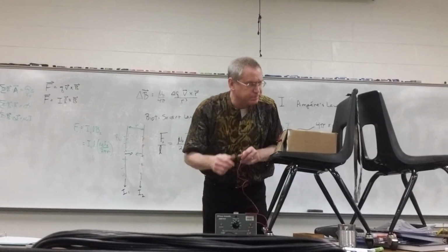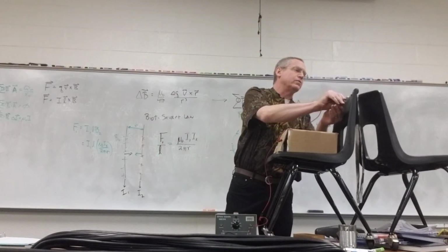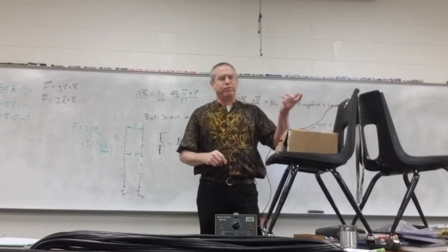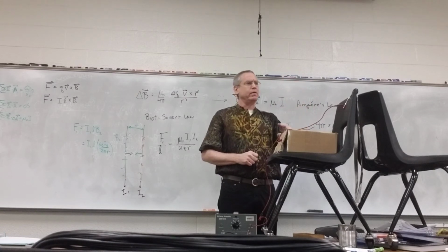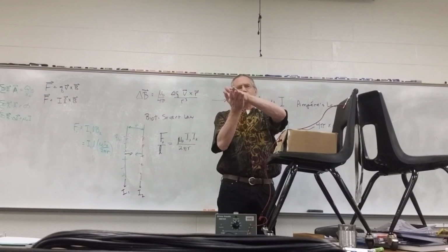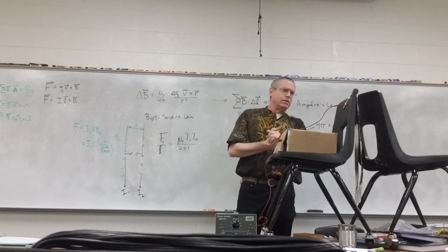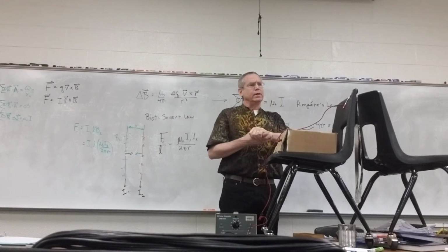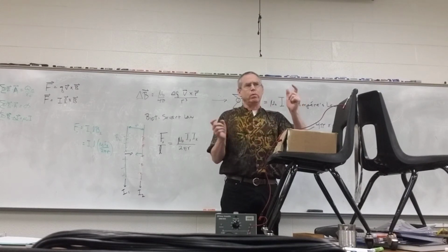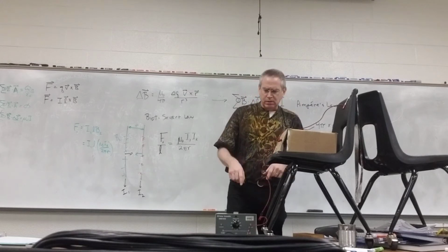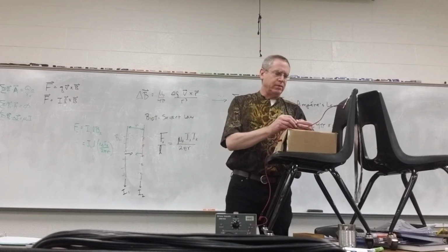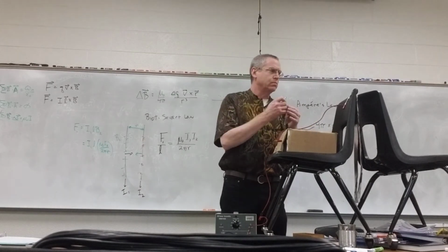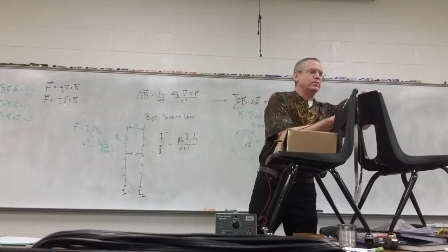This is turned off, right? Yeah. Now, one thing about this is because this is just an aluminum strip of particular length, remember that resistance depends upon resistivity times the length divided by the area. There's not a lot of area there, it's a flat piece of aluminum foil, and the distance isn't very long. And so, primarily because of the length, there's not a lot of resistance, and so we are going to quickly trip the breaker in this. So it's just that we can easily reset it, but that is an issue so it won't be sustained.